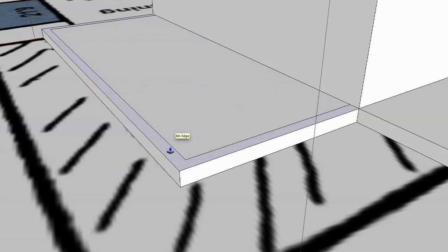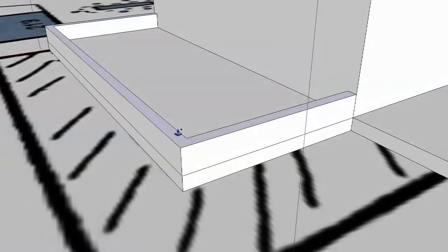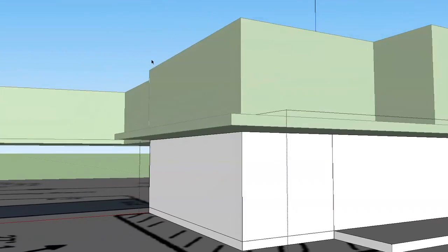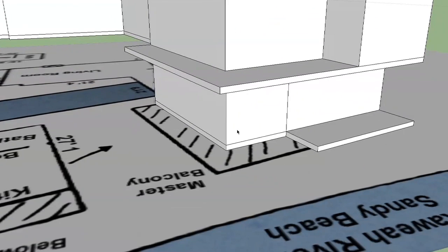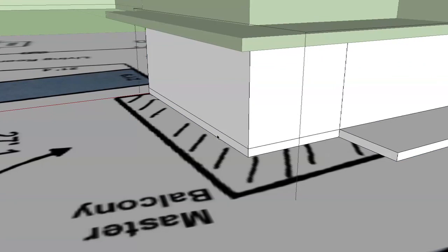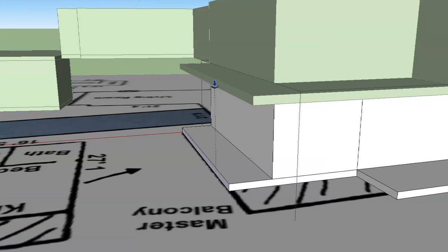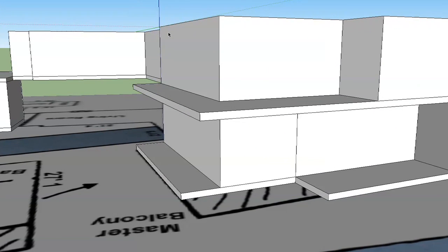And then I'll use the Push/Pull tool. Hit the Option key, so I'm pulling up a copy. That way I keep this dividing line down here. And I'm going to pull it up and just snap it up to the top like this. There we go. So you can see now that's going to be our screened-in porch. And I'll go back into the group again, and I'll extend this pad out and snap it up to this top porch part here. And that'll be our real exterior porch.